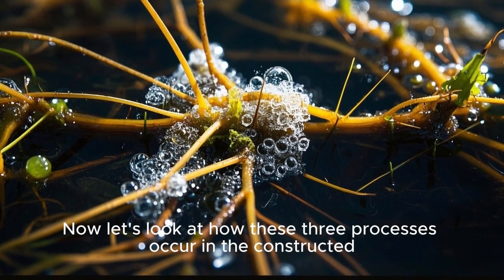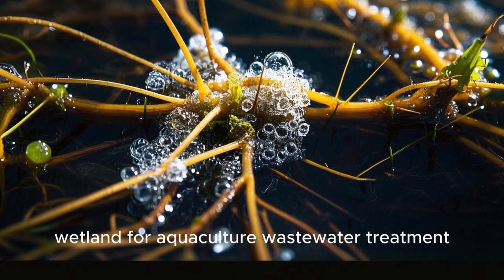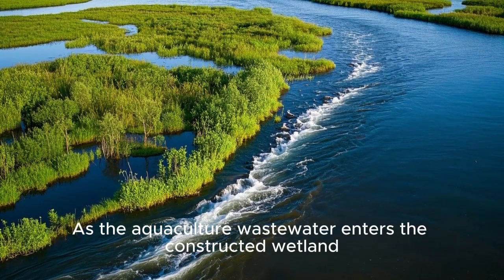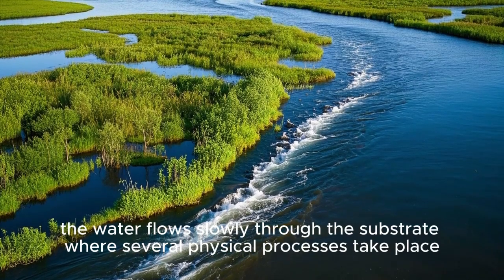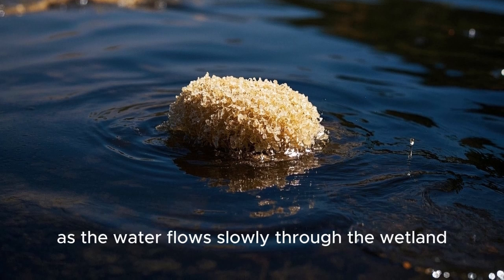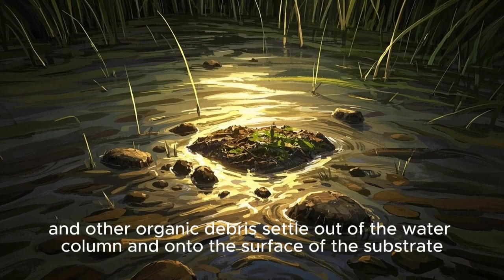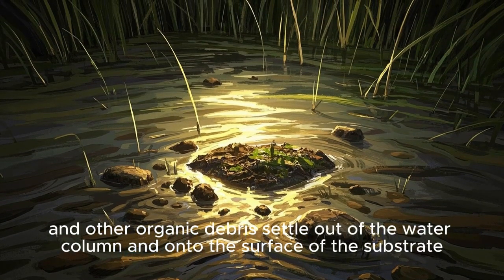Now, let's look at how these 3 processes occur in the constructed wetland for aquaculture wastewater treatment. The first process is physical. As the aquaculture wastewater enters the constructed wetland, the water flows slowly through the substrate where several physical processes take place. One of these is sedimentation. For example, as the water flows slowly through the wetland, suspended solids such as uneaten fish food, fecal matter, and other organic debris settle out of the water column and onto the surface of the substrate.